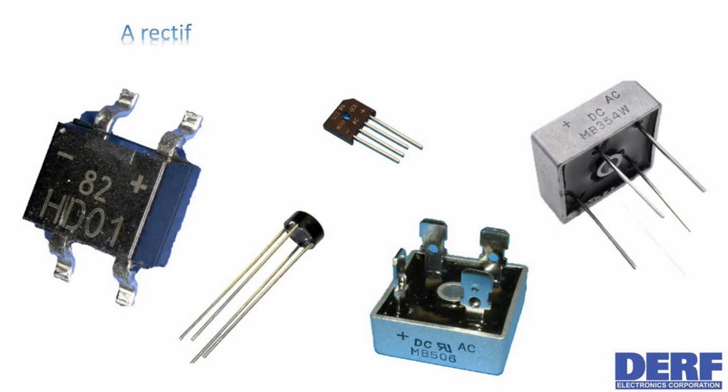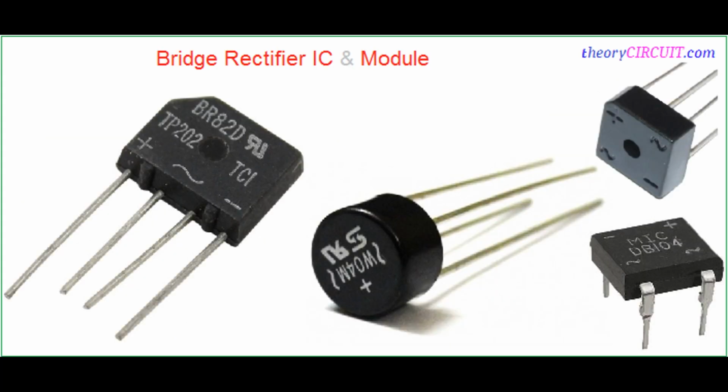Rectification: during the positive half-cycle of the AC input voltage, the diode is forward biased, allowing current to flow through it. This means the diode conducts and allows the positive half of the AC waveform to pass through unchanged. Blocking: during the negative half-cycle of the AC input voltage, the diode becomes reverse biased, effectively blocking current flow.